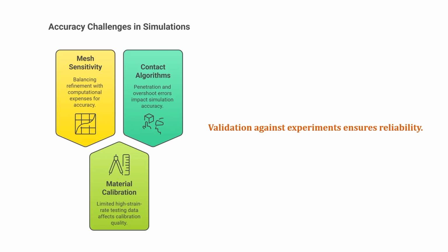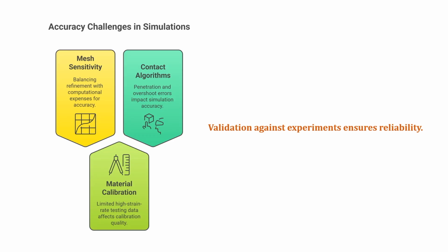Then comes the case of contact algorithm. We have seen that the blast and impact are very much dependent upon the contact algorithms associated between the impactor and the target body. So, problems like penetration, overshooting error, errors in the impact simulations are the Achilles heel. So, they should be properly incorporated into the finite element simulation.